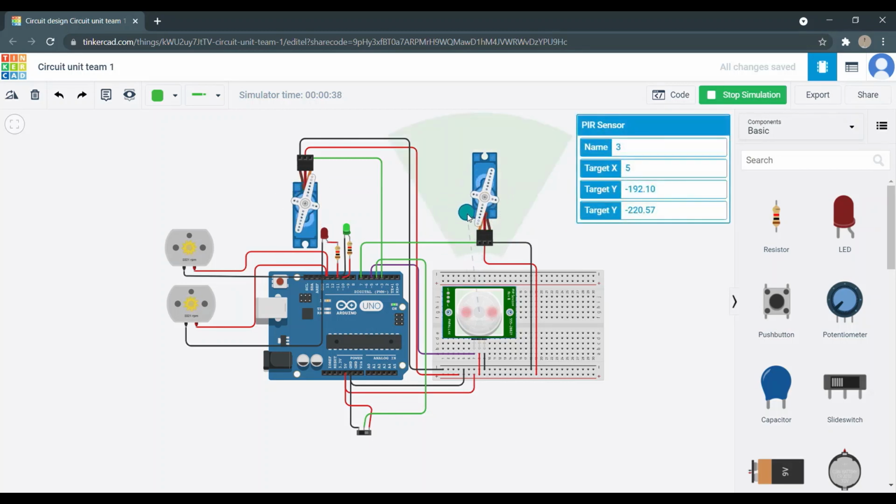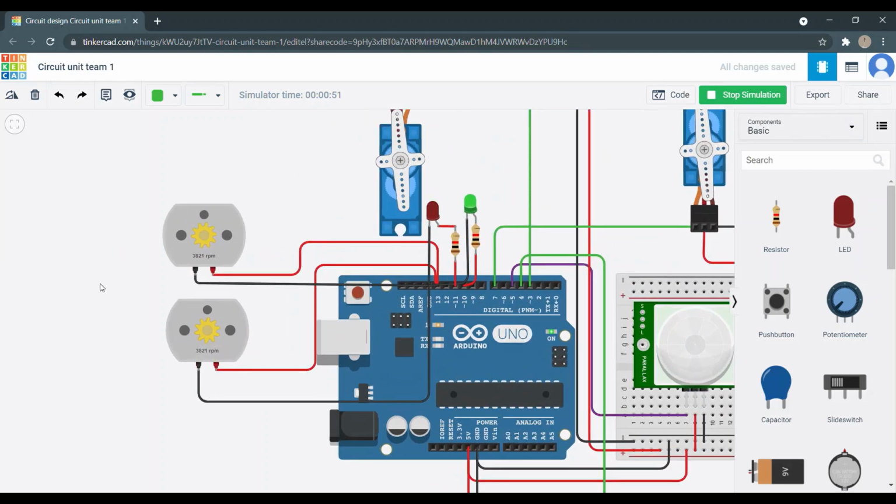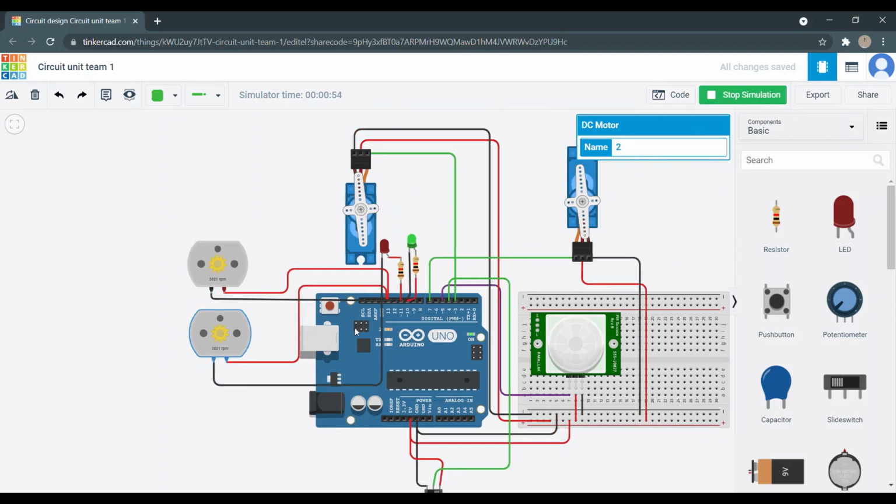The circuit is designed in such a way that the bin flap opens up automatically and simultaneously with the top flap when the PIR sensor detects the cup. Meanwhile, the 2 DC motors are on and running, one for the crank for the pressing of the cup and the other one for the blades to crush the cup.